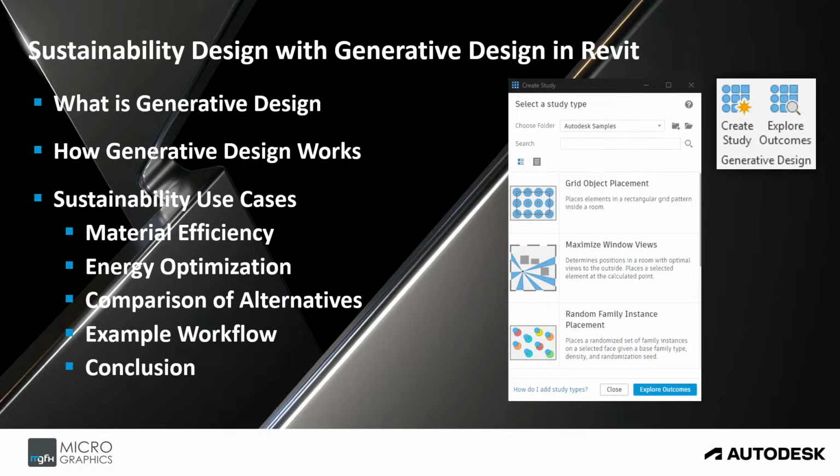Second, running the generative design. The architect uses generative design to create thousands of configurations, testing different orientations, window layouts, and structural features. Each iteration is evaluated based on daylight performance, ventilation efficiency, and overall energy demand. The algorithm assigns scores to each option, highlighting the best performing alternatives that align with the initial sustainability goals.